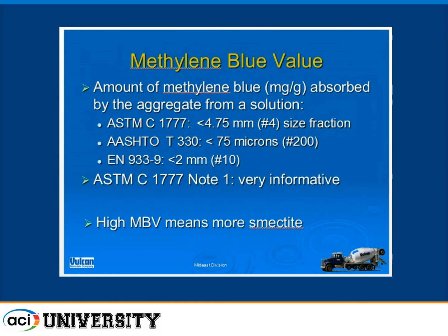A very new standard just got published in the last couple of years. ASTM published a standard called ASTM C1777, and frankly, I wasn't aware that this was published until I was preparing for this presentation, and I find it to be very, very interesting. In there, there is a Note 1 that is very, very informative. It contrasts and compares the ASTM standard testing versus the other more established testing methods like AASHTO T330, and this is, I guess, the European standard.